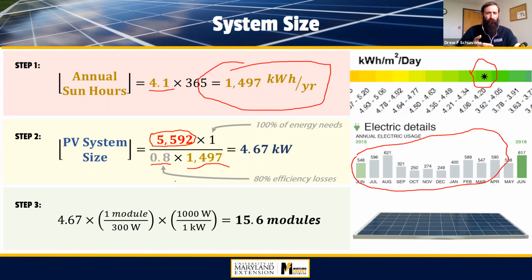We looked at that in our webinar last week. This efficiency rating that I'm using, 0.8, is a pretty conservative estimate for the losses that you'll have in the wiring, the inverter, and other parts of the system where you are not working at 100% efficiency. And so 0.8 is pretty conservative. I'll share where some of those numbers come from momentarily, but I'm using a conservative 0.8.